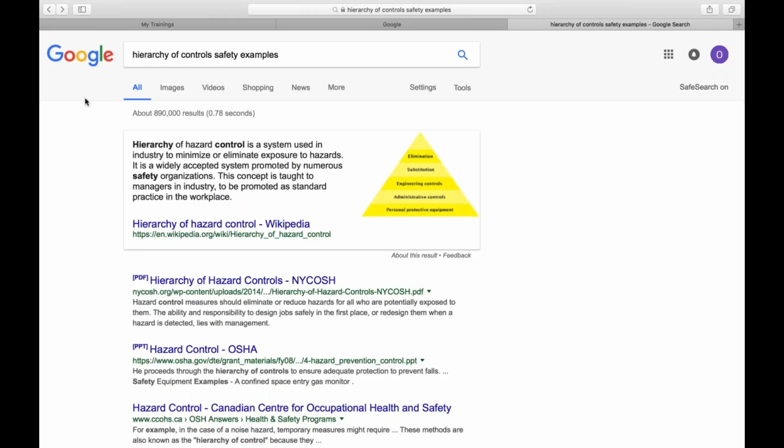So we make sure that we have all of our safety data sheets available for all chemicals, and have reviewed them in order to know that we're safely working around the chemicals on the work site. These forms describe the hazards that the chemicals may present. They list any precautions, instructions for handling and storing the substance and using it, and also outline emergencies, fire extinguishing, and first aid procedures as well.